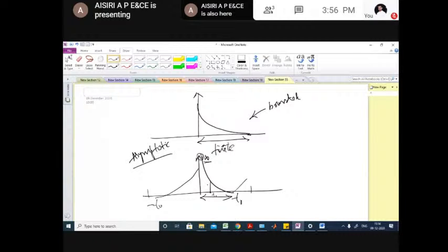And then we are saying a bounded signal is finite. I'm considering this particular bounded signal. This can be finite, or it can reach up to infinity. So you cannot have a guaranteed statement for this particular signal to be finite. If you have a bounded signal, there is no guarantee that it is finite. If you have a finite length of sequence under asymptotic condition, it will not be bounded. And according to the statement C, the bounded signal will not be zero for some T naught. So all three statements would go wrong.